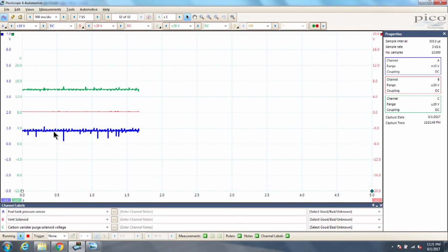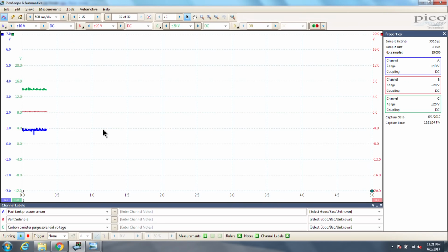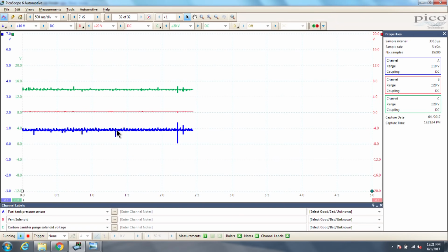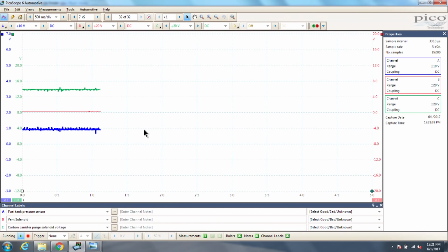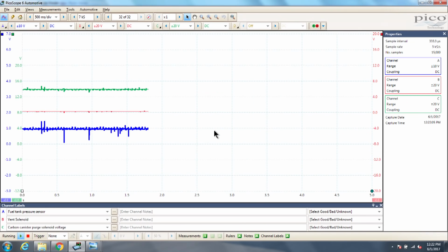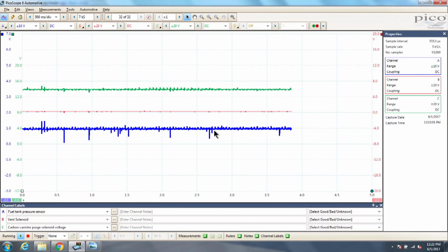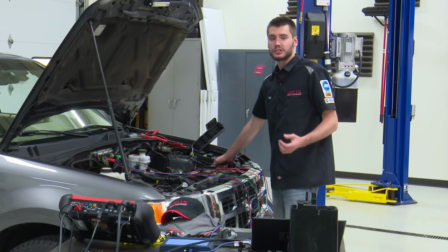So if our threshold were 1 and we had to do it for 15 seconds and maintain under 1, if this was, say, 15 seconds, we've currently crossed the threshold. We're above 1, this would fail the test if that was our threshold. Okay? And then if we pass the test, if the computer says, okay, I'm happy, I'm not leaking, it's going to open up the vent, just like I talked about over there.